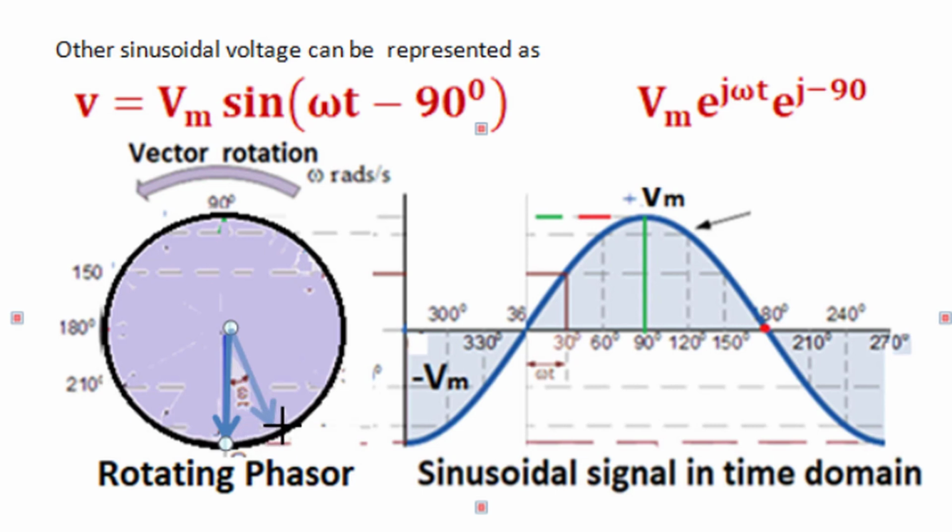Rotation of the phasor in the anti-clockwise direction, after a quarter cycle, brings zero instantaneous magnitude. A half cycle will produce a positive peak instantaneous magnitude as projection on the vertical axis, and one complete rotation of the phasor generates one cyclic alteration on the vertical axis projection, as represented here.